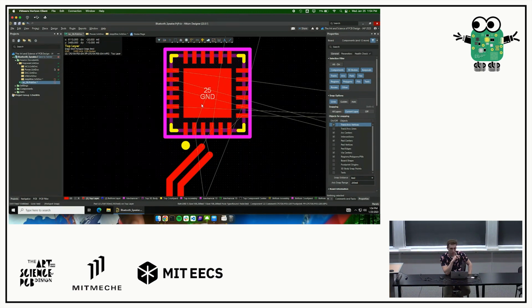You can still do it. You just have to model the impedance of the via, which is coincidentally what I'm doing right now. But yeah, avoid it at all costs. That starts to matter a lot more as you go to higher and higher frequencies. USB is pretty quick in terms of frequency because that's how I'm putting HDMI signal out on the monitor right now. So USB cares a lot, especially Type C and such.